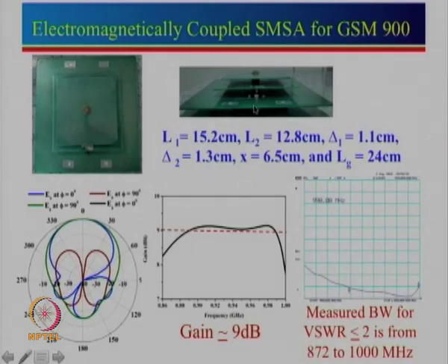So you can see that these patches are really nice, because in this particular case, unlike in the case of planar configuration, where there is one patch in the planar, another one here and another one here, there is some phase shift happening because the phase center is at this point. So compared to this, the patches experience a certain phase delay, but in this stacked configuration the phase center remains the same, and that is why the radiation pattern variation over the bandwidth is very small, and gain variation over the bandwidth is also very small. One can see that it is almost flat, and this is the radiation pattern.